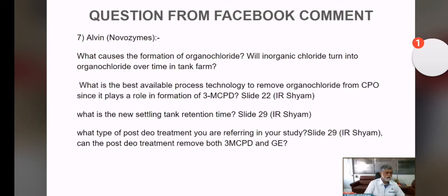I think there are certain dynamics involved in the separation between the two phases. I studied this probably 40 to almost 50 years ago, and I've forgotten most of it. It is best that somebody who is conversant in that topic addresses that question. There is a tendency for us engineers to say, he did it, let me copy paste and do it in my refinery. I think that is where a lot of mistakes have happened. We should take the trouble of looking at the design, studying it, doing the calculations, and letting it go from there. It also may depend on the space that you have available to put up those tanks. Of course, the longer the better. If you can do something with a very long retention time, it will probably give you better separation between the two phases.